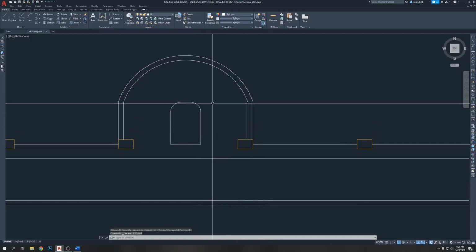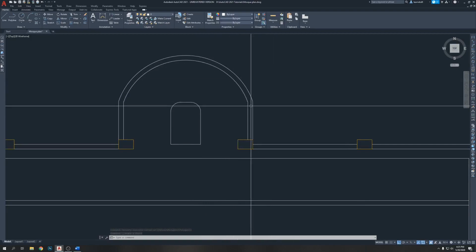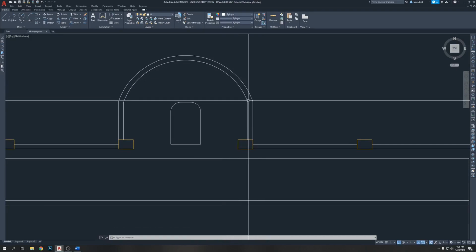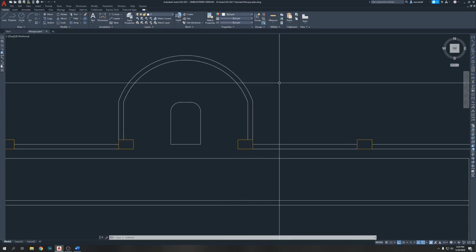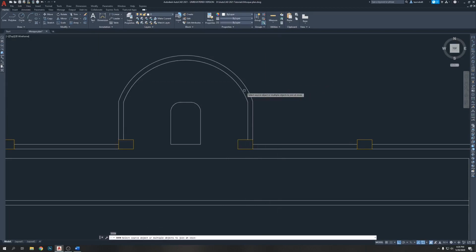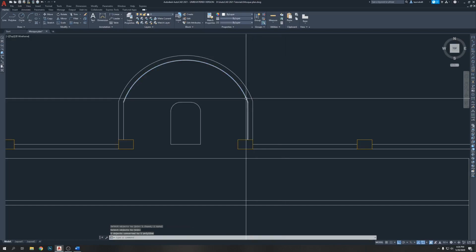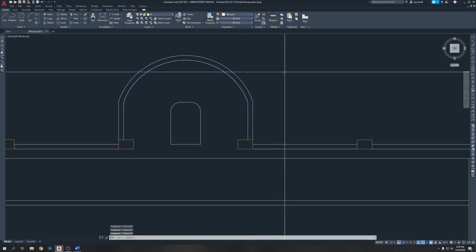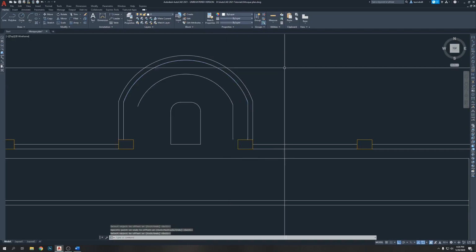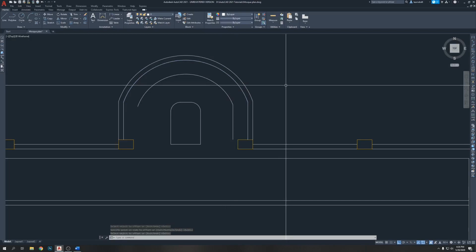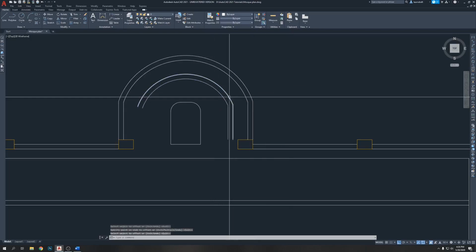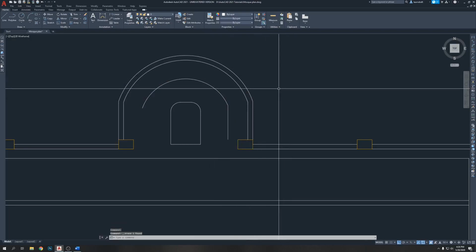Now we need a little bit like a stair here. What we're gonna do, we're gonna poly edit these two lines, put together, or let's join them. J, enter, click, click, enter. Let's see, join, yes. So now offset for like 18 inch, just for Imam to walk, 18 actually is gonna be very small for him. Offset 6 more, and take out the center line. This looks good.